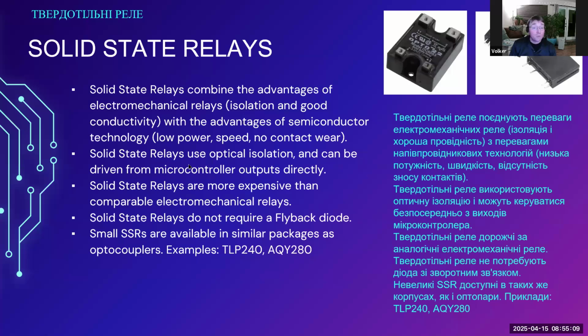Solid-state relays. Because relays, the standard electromechanical type, were so common and versatile, the industry tried replicating the relay functionality with solid-state semiconductor devices. Solid-state is really just a different name for semiconductor devices. They combine the advantages of electromechanical relays, isolation and good connectivity, with the advantages of semiconductor technology: lower power, higher speed, no contact wear.